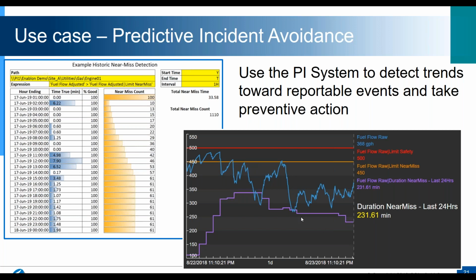So we can take this information and break it down. In the PI system, we're doing a count, this is a one-day period from yesterday to today, and intervals of 1 hour. For each hour, how many times did that blue line cross the threshold? And for each hour, what's the aggregate number of minutes in this case that the blue line spent above that threshold?